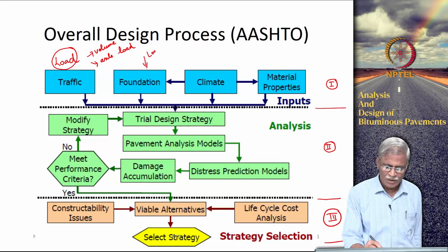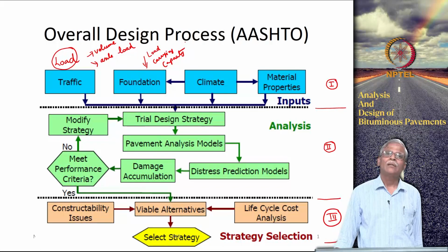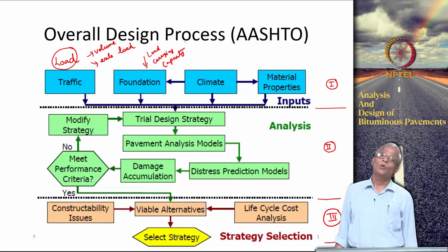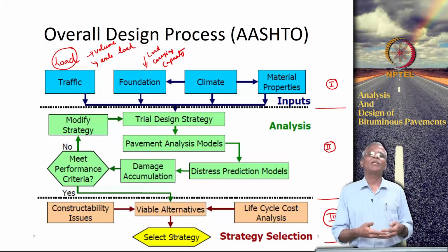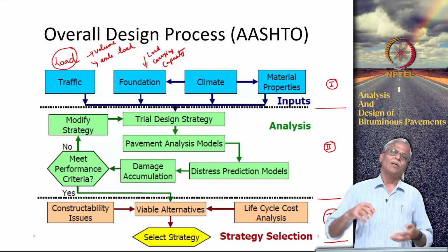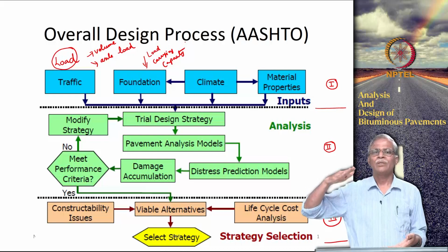Okay. So, the most important thing is, what is the foundation? You can say the load carrying capacity, and this is where you will also be able to relate what is called a compacted subgrade. So, many of the design charts that are given in IRC 37 talk about the thickness to be provided on top of a subgrade having 10% CBR.